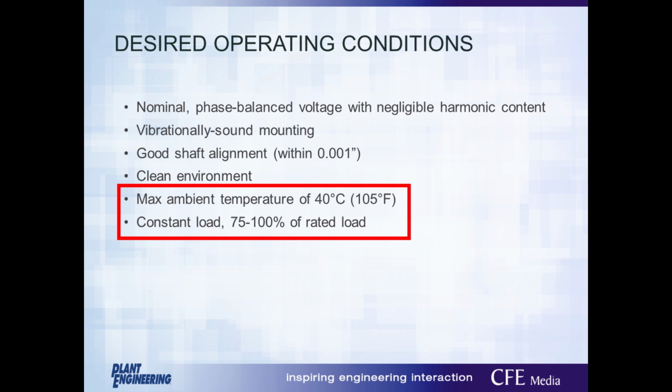Heavy overvoltage can be a problem. But what you don't want to have is undervoltage at your motors. So if you were to check voltage at your motor terminals and see voltage under the nameplate rating, you definitely want to troubleshoot to determine the cause.